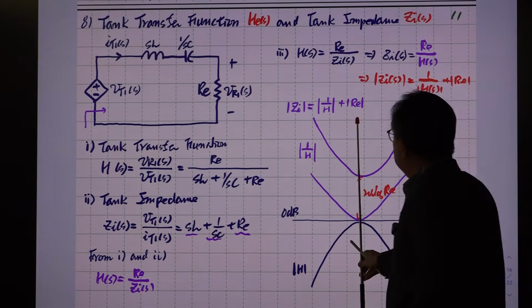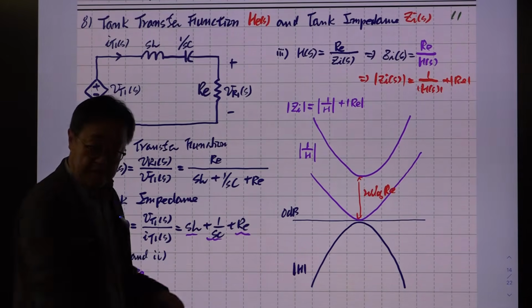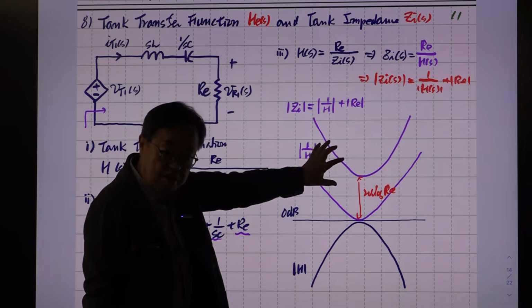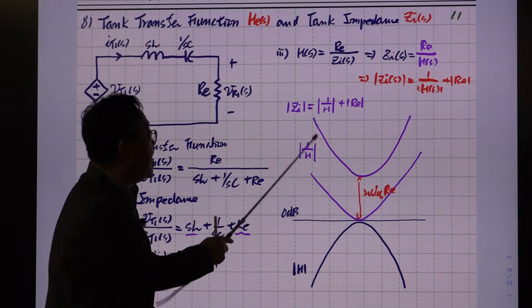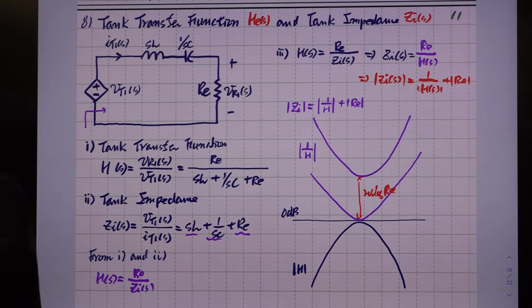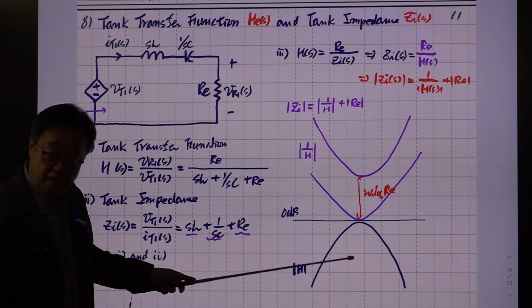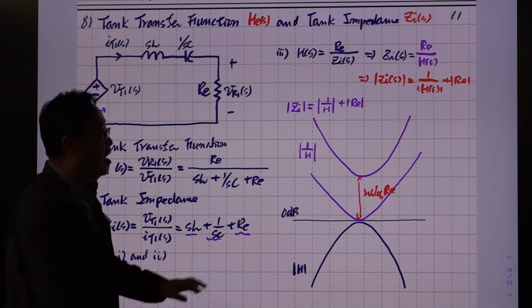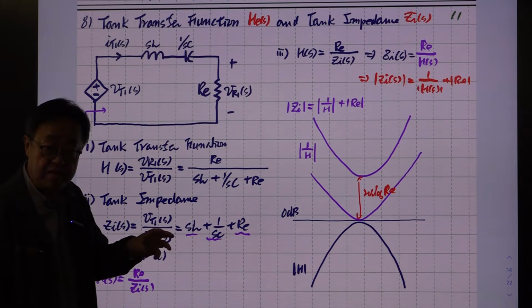And in here, this is increasing. Then this GI has this capacitive slope. So this area is GCS, GBS, okay? You don't have to watch this GI all the time. You are doing this all the time, right? When you are designing a resonant converter, the first thing you want to do is plot this curve to estimate the DC in DC out gain. If you know this shape, then you can figure out whether you will have GCS and GBS. Okay.